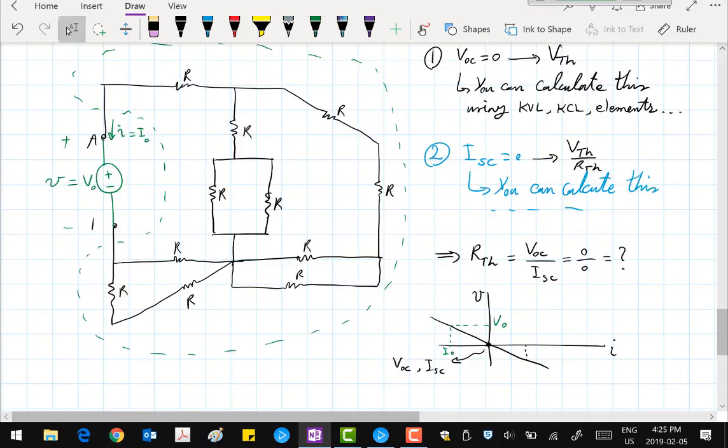So here we have a question: wouldn't the current be the other way? Now, in reality, if this V naught was a positive number, and if I calculated what's happening in the circuit with this convention of current, I would get a negative number, which means the current is actually going in the other direction, right? But that doesn't matter. What's important for me is to stay consistent with my convention here.